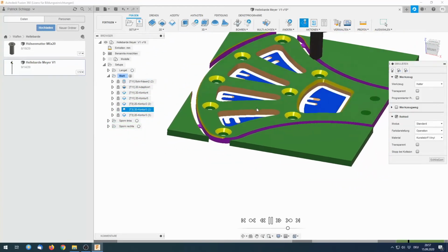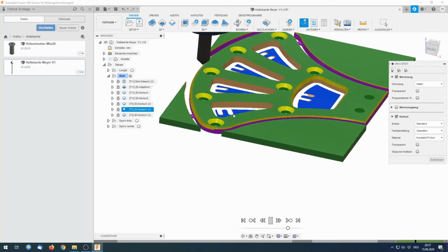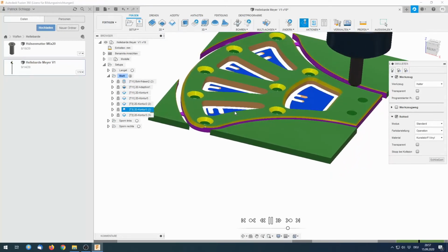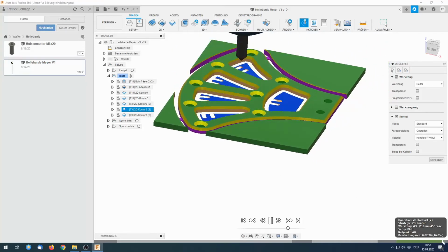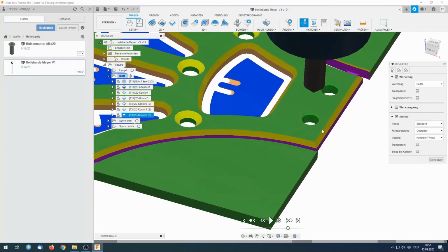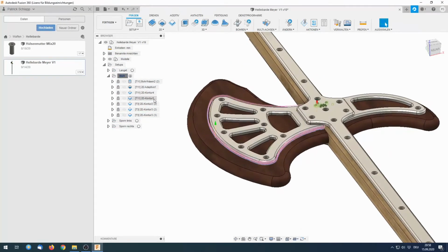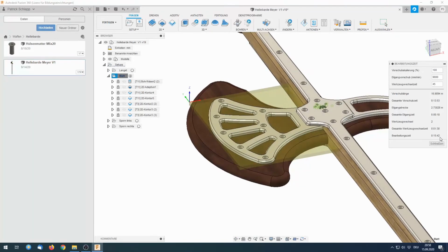And it also doesn't pose any risks of getting cut on a sharp edge, which would of course be pretty dangerous in HEMA. And for finishing, these two holes will get a small chamfer around the outside, and that's it. So, neat thing about CAM is I can already look how much time this part will take to machine, and it would be a 15 to 16 minute part according to this.